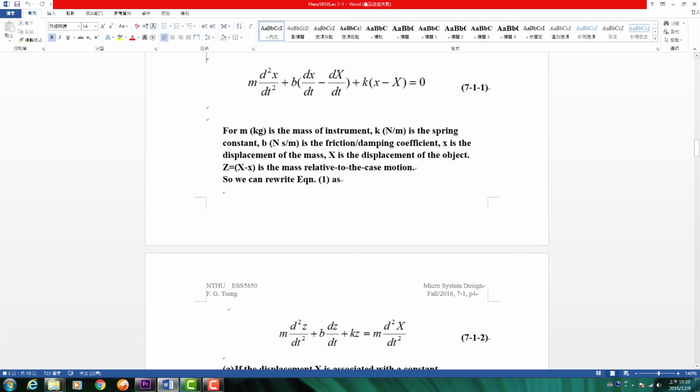So this dynamic process will be balanced with the acceleration, the acceleration from the large mass. Okay. When the large mass encounters acceleration from outside, the acceleration will give some dynamic action onto the system. The system means the small mass plus the large mass. The relative distance change, okay, will be according to the outside input of the acceleration.